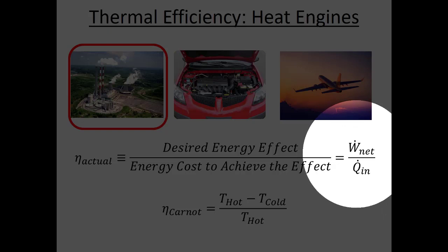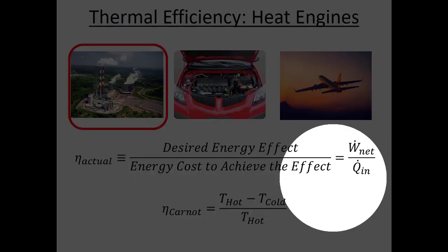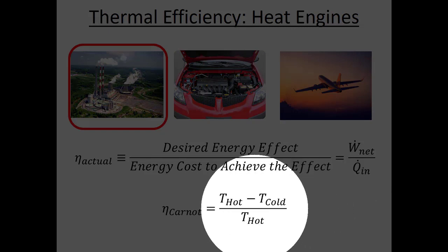Now, for Rankine cycles, we're typically putting that power out on the grid. So this particular equation for thermal efficiency will always be true for heat engines, right? But if we want to look specifically at ideal heat engines, or what's the highest efficiency we can get, because we all know, hopefully by now, that the highest efficiency we can get is not 100%. So we're limited because of the second law and the irreversibilities that always happen, right?